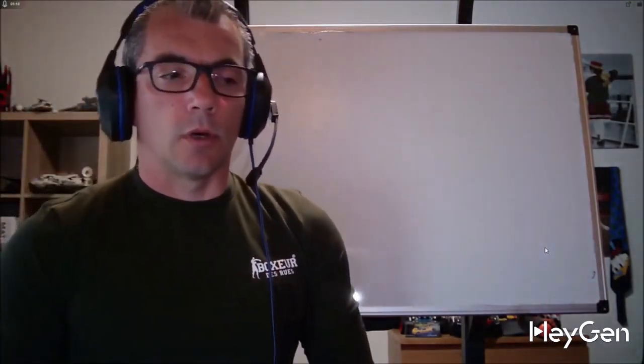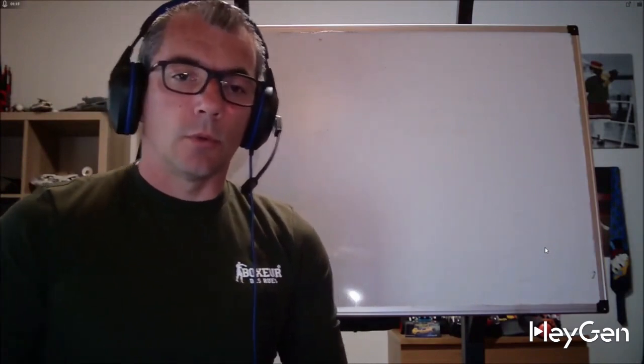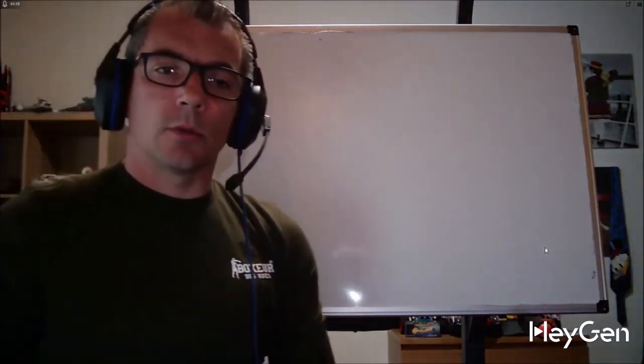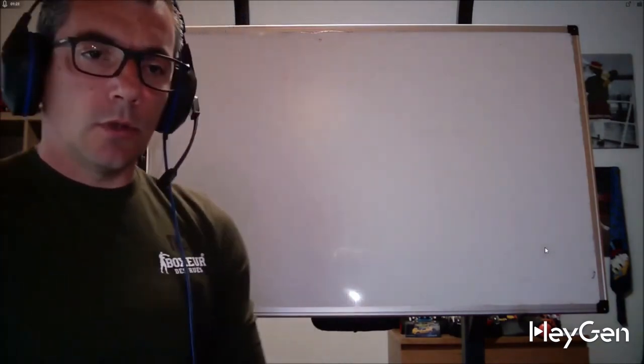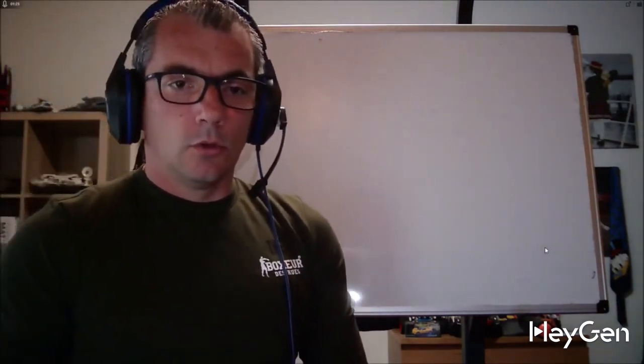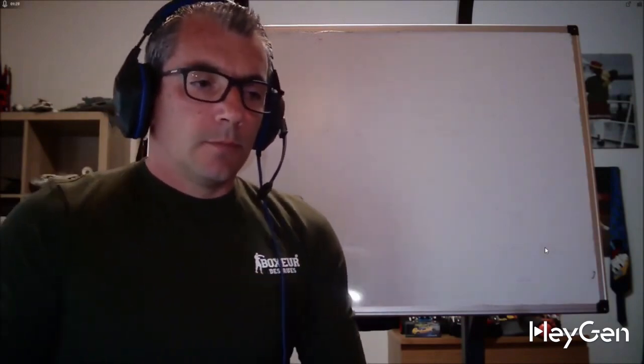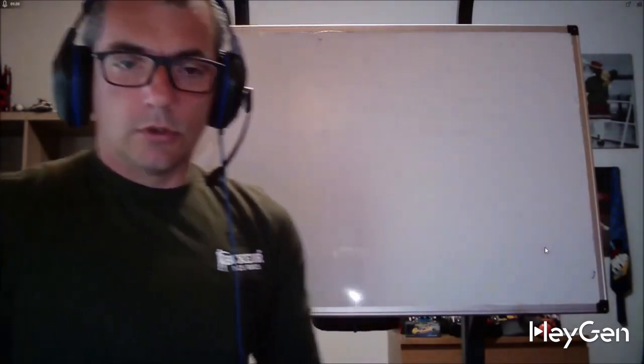Previously we explored clearing a part with point-to-point programming. Now, on the whiteboard, I want to explain the macro concept. Consider a piece like this. We're not focusing on dimensions now, but after facing it, we have material left to clear. Today we're talking about the roughing macro. I call it a macro, but in the manuals they refer to it as fixed cycles. So I apologize for not making that distinction.